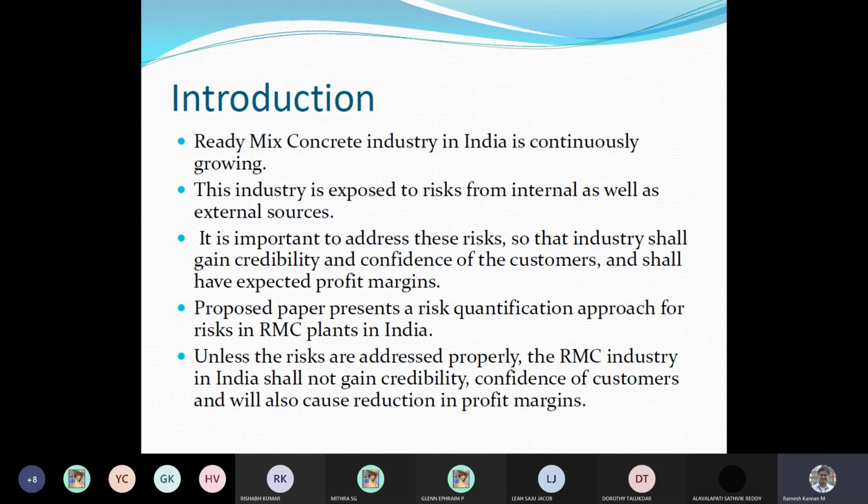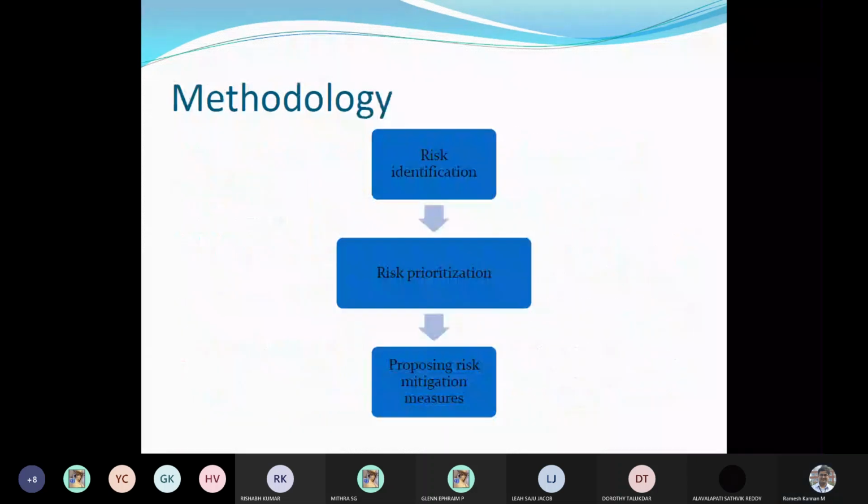Those things are pretty much the general process, with the objective to transmit concrete from one place to another. But then there could be some delay in the traffic, or the routes were blocked, and the estimated time gets exceeded, so your concrete started setting. Those things are a kind of risk, right? So these are risks associated with the RMC. If you own an RMC or an RMC truck, then you will be considering all these things in much detail. So this is very important. Kindly pay attention to this.